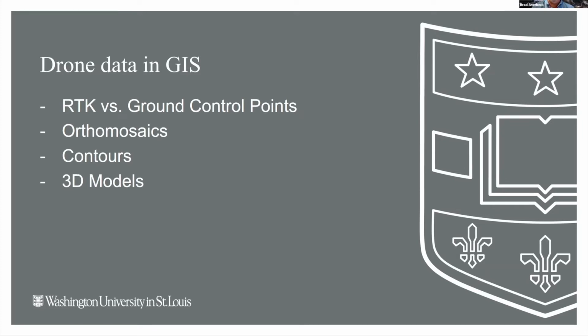But we also use ground control points. And one of the reasons that ground control points are important is because it actually gets us down to about a 1/2 inch accuracy. And it also ties us into the vertical control system. Because RTK doesn't always, because of the processing software that we have, they have a limited number of vertical data sets that we can use as far as coordinate systems. So currently we're tied into Geoid 03, which is NAD 1983, I believe. And Pix4D, which we have, doesn't tie into that data set.